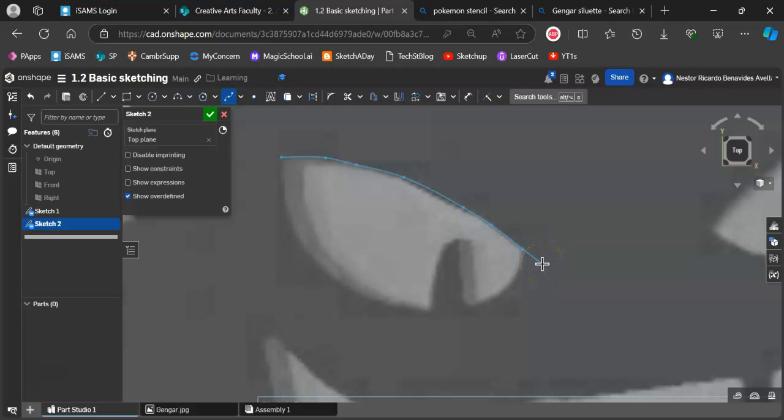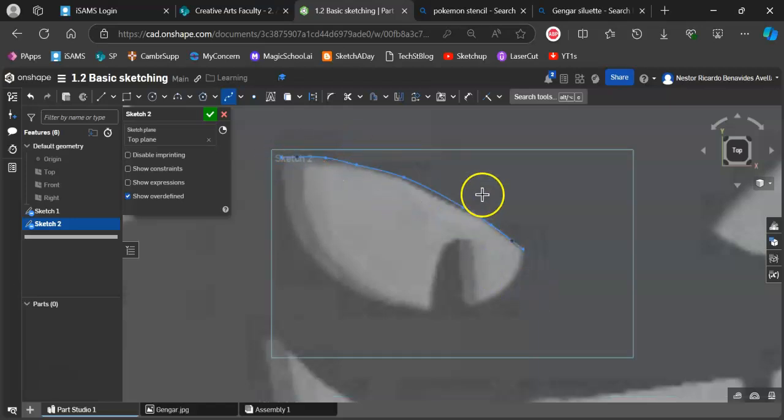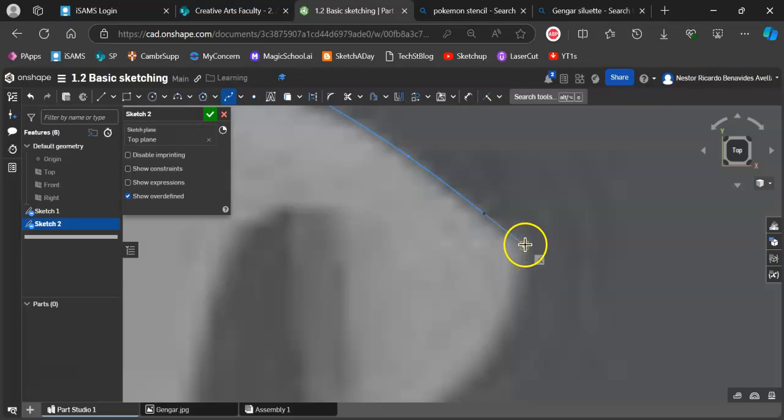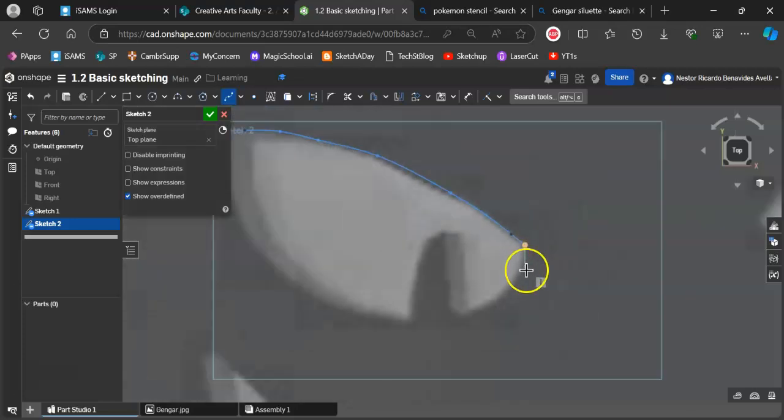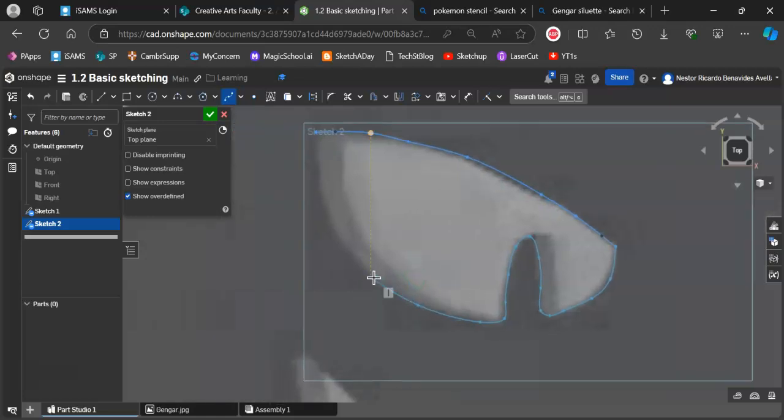let's say a pointy corner like this one, I'm going to hit escape. So my spline will be finished here, and then, really carefully ensuring that my first click is actually on my final dot, click here, and then continue making the line. Somewhere here, somewhere here. You can click, it's up to you. It's up to how much detail you want to have in your drawing in terms of the curves and everything else. But literally all I'm doing is clicking and dragging.